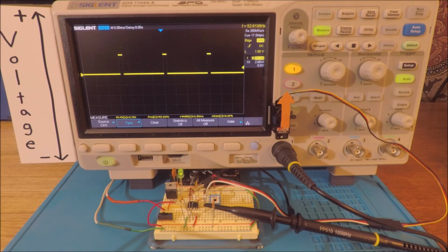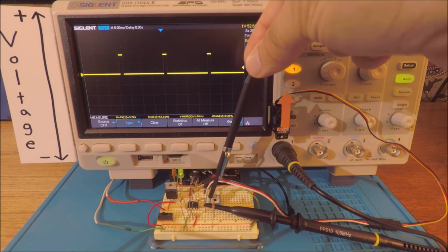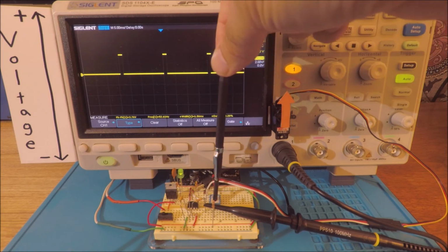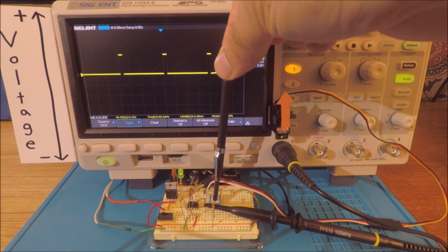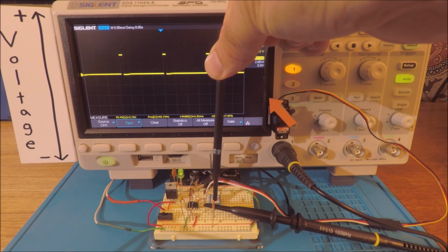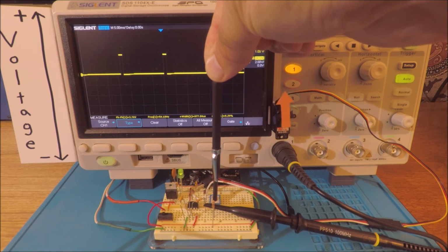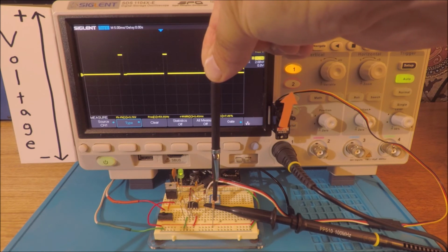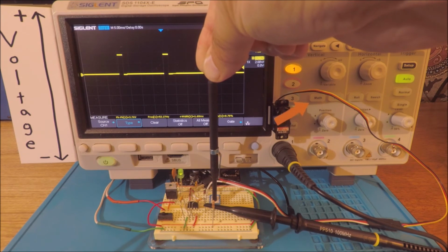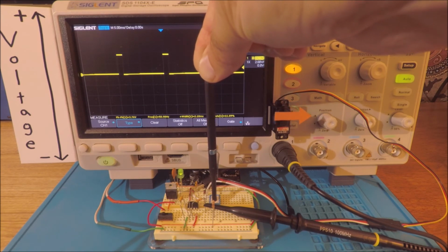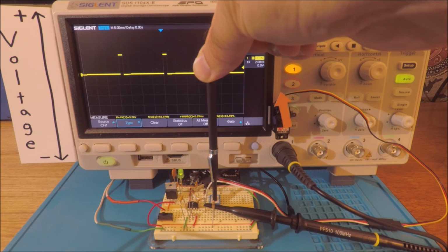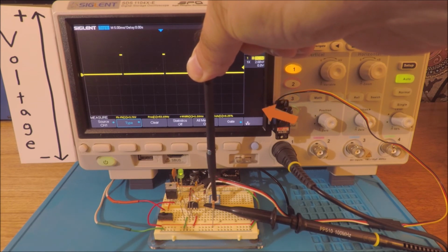Here I've connected a small submicro servo to the circuit, and I've mounted it to the front of the oscilloscope with an indicator so that you can see its rotation. And now this is at the center point. We can change the pulse width. We'll decrease it down to 1 millisecond pulse width, and then we'll increase those pulse widths back through neutral, 1.5 milliseconds, and up to the maximum amount, 2 milliseconds. And we can see the servo operating in concert with the commanded signal.